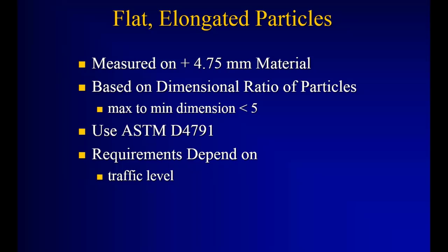We ran this with QC/QA in North Dakota for a while, but basically I've never seen a failing flat and elongated test in North Dakota. And you see it very rarely in sand and gravel pits, because Mother Nature kind of abhors these flat and elongated shards, if you want to call them that, or arrowheads.